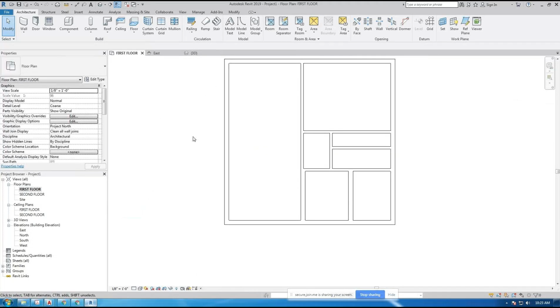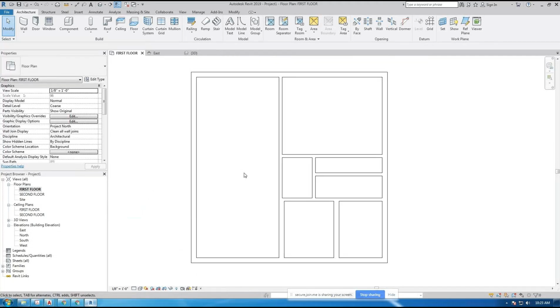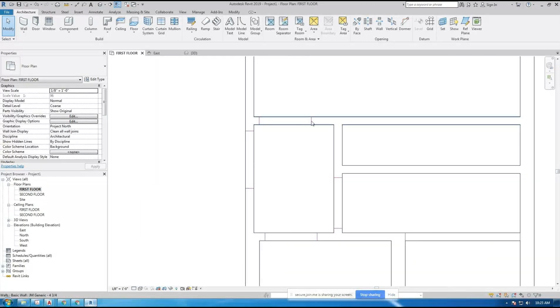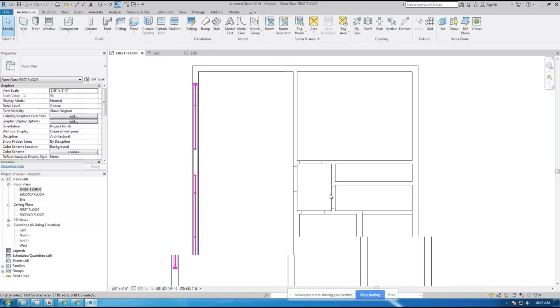Let's go back to plan view. Click here in plan view. Let's draw some doors. I have no idea where the doors are because I'm covering up my AutoCAD drawing completely because I'm in hidden line. This is why wireframe is useful. There. And in wireframe, I can see there's windows here, curtain walls. I'll draw those later. But here, I can see some openings in the walls here.